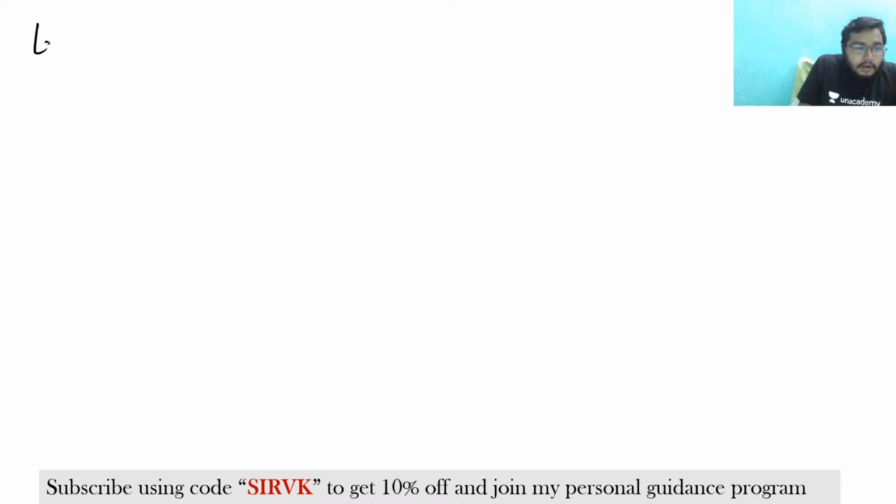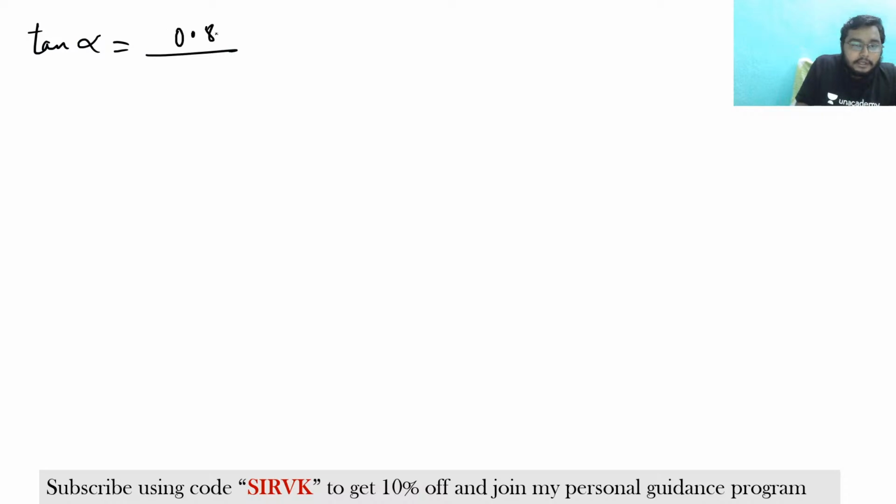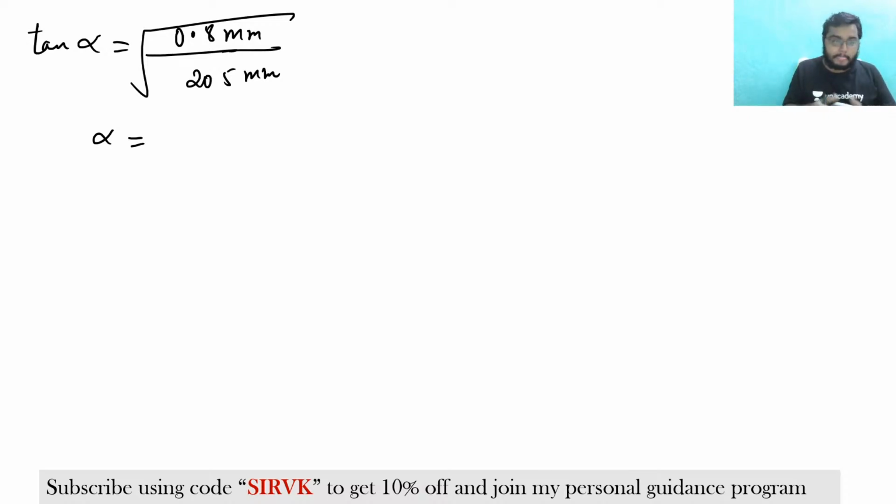So tan alpha would be, see, that is root over delta H by R. What is delta H? Is it 0.8 mm? Write it here, 0.8 mm by radius of the roller. What is the radius of the roller? Is it 205? So that would be 205 mm. And from here you will be getting alpha is equal to,